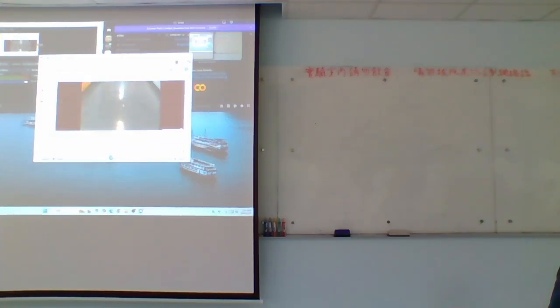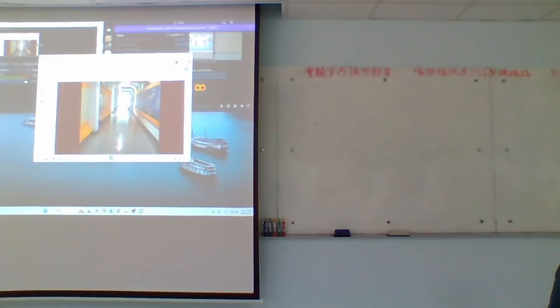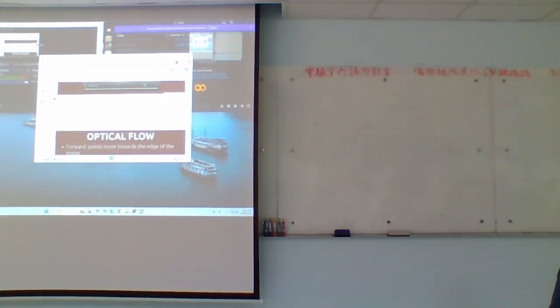And this one, actually, technically, this would be monocular, a single camera visual SLAM. There's also stereo vision visual SLAM algorithms which perform better in the sense because they can get the depth information easier or more robustly.